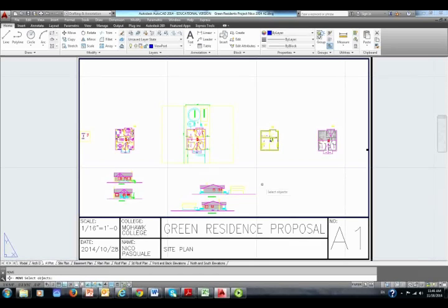Now one could work with better fonts, but let's say that I am happy, except this now doesn't look very good, so I am going to delete this. And I'm going to use something that I taught you in my earlier tutorial on title block, and I'm going to simply copy it and then click on the text and change it to, see what happens to the text, A1 plot layout assignment.